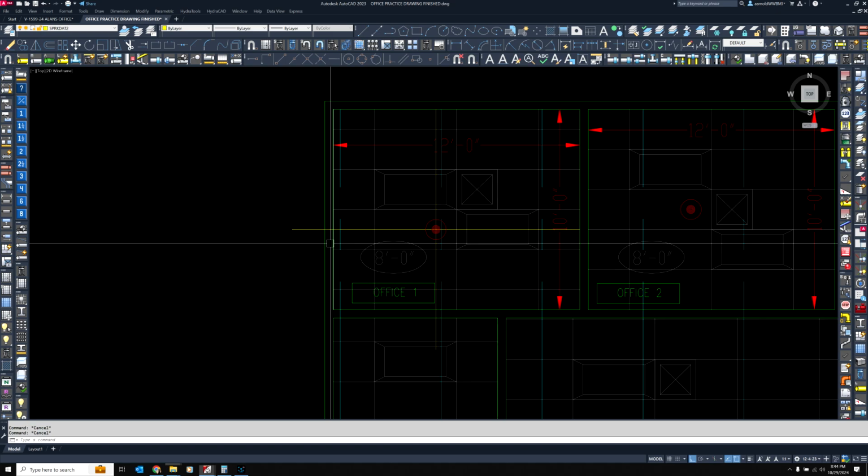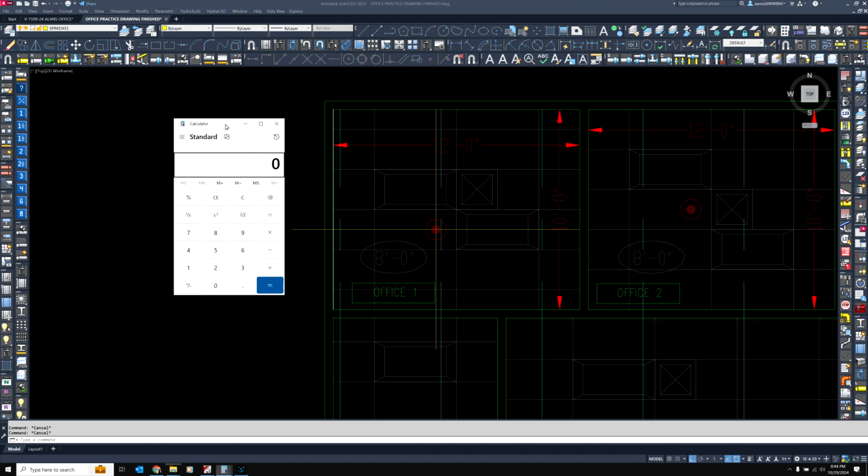Hopefully that makes sense. And if we're talking about this so we can visualize it all, we have to double that 7 foot. 7 times 2 is 14. And 14 times 12, because 6 times 2 is 12. Now we're 168 square feet instead of 120. If this sprinkler head were placed dead center in the room, it would be protecting 120 square feet. But today, that's not doable, and we have to do the math per code, which is doubling the distance off the wall.